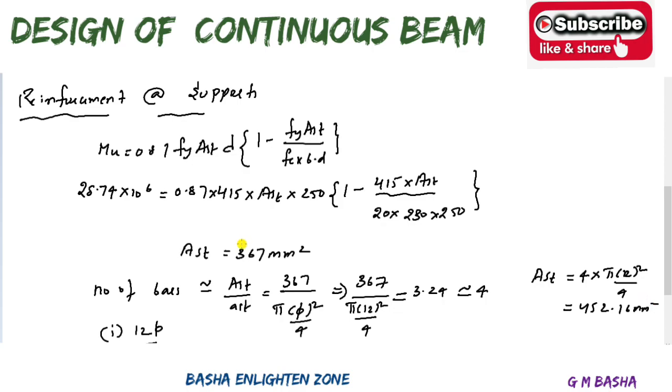See here friends, the area of the steel required is 367. The obtained value here will be around 452. So the area of the steel required is lesser than the area of the steel we are going to provide. So this is the provided value. So it is on the safe side only. Therefore, I will go with this value without any other try.